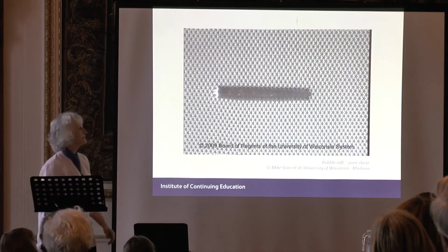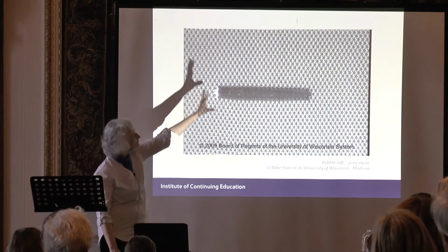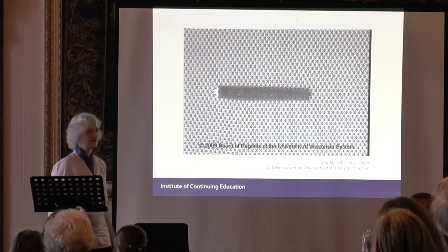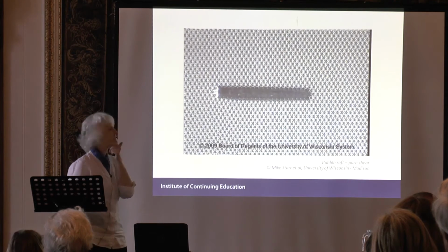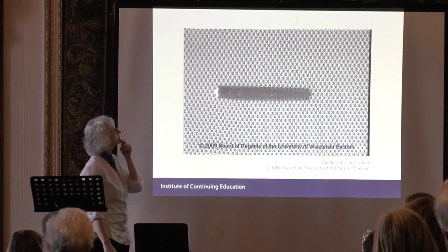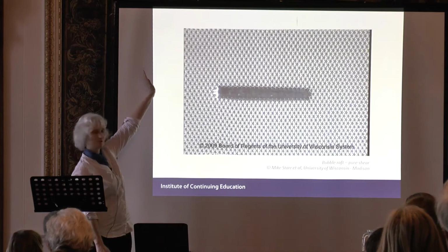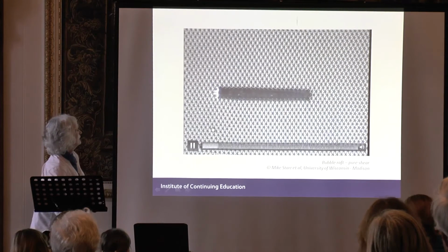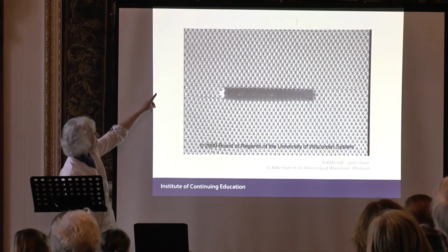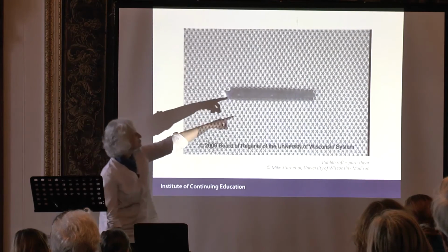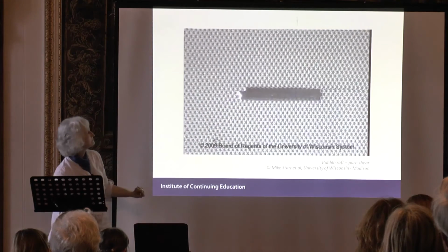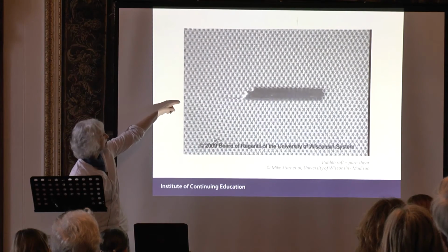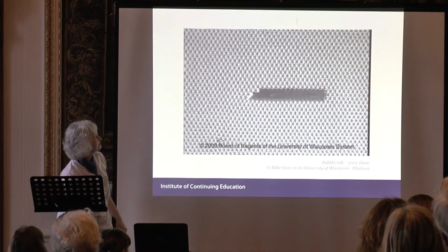Let's go back to our bubble raft. So this time we've got a pretty much perfect array of bubbles pretending to be atoms in the metal. What happens now when we apply a load to it? So this thing is going to get pushed from top left. Okay, so it's being pushed from the left, and do you see how it's shunting along? There's a little gap in the middle, above the gap, to the right, and down here on the left.